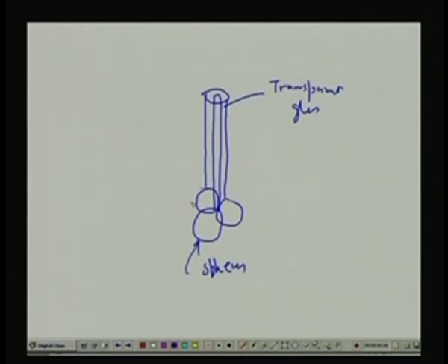So, what will happen? This is put on the upstream side. What will happen if the water level increases? This float will go up like this, and if you have a graduated scale on the glass itself, I can measure this height and calibrate the height in terms of flow. These are basically for balancing. If you use a single one, there is the problem of balancing.